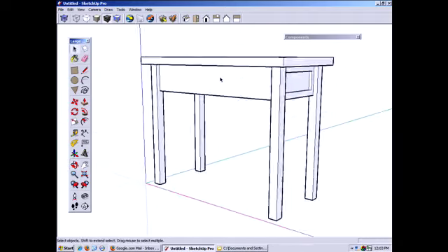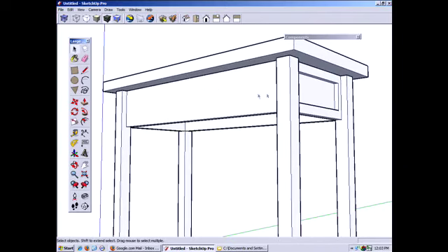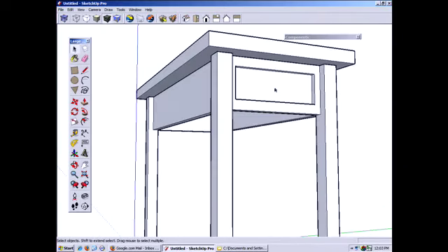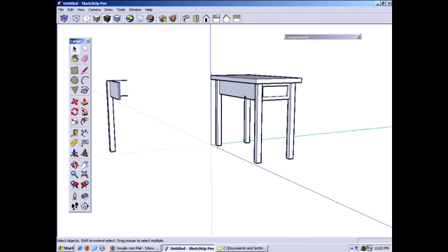Now, why did you delete the surface? The reason I did that is I have found that when you create components like this, that leftover surface, if you don't delete it, sometimes you get flickering, and it's just sort of a little indicator that you still have something there. We're not seeing it very much in this example. It's just something that I've found does get in the way. So as a general rule, I usually delete the surface, hide the edges.